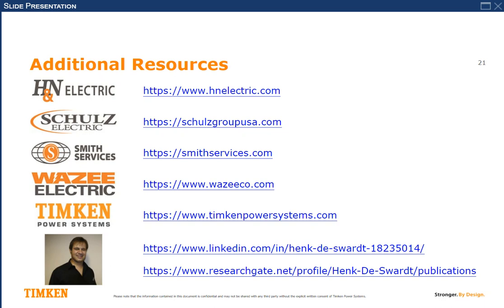The other temperature one is where you have general core heating, if the entire core is getting hot. Again, you will take a thermal camera, and any increase of 10 degrees above body temperature will tell you that core is bad. Now, that's just in brief. Obviously, there are complete studies, and if the customer is interested, I can give them some information on how core testing is done. But that's in brief.